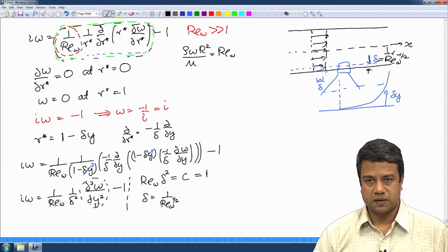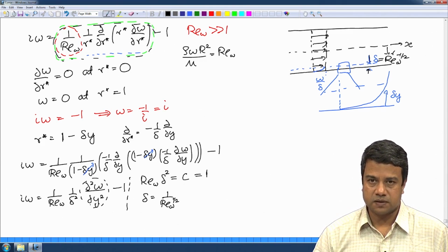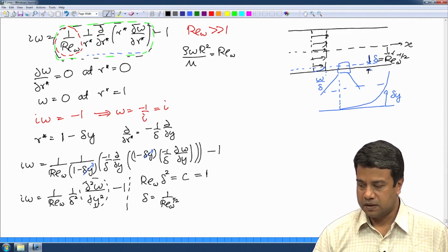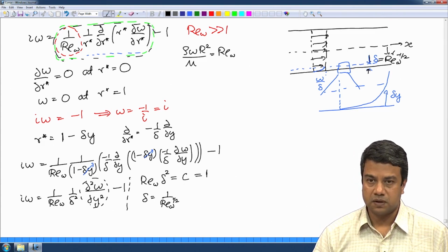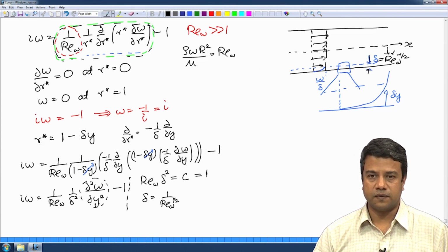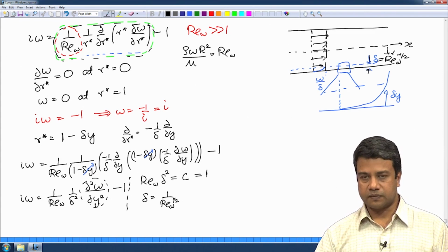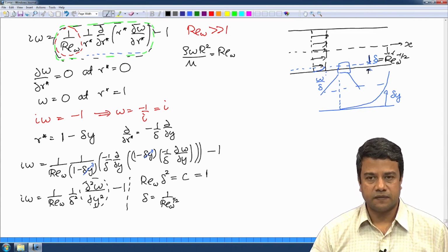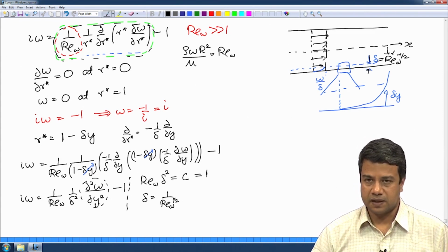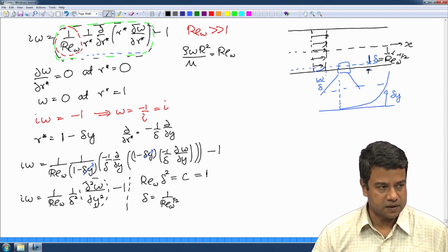Physically, the zero velocity condition at the wall is because of the retardation of the flow close to the wall. The momentum diffusion to the wall slows down the fluid close to the wall and reduces the velocity to 0. This physical effect had been neglected when we neglected the viscous term in the conservation equation, and therefore, we were not able to satisfy the boundary condition.